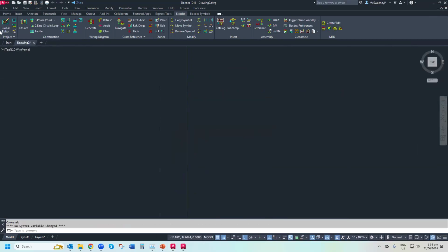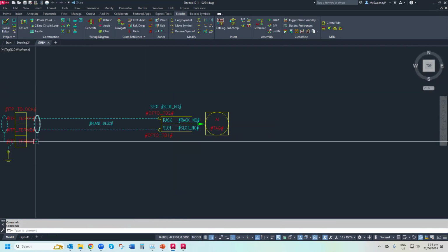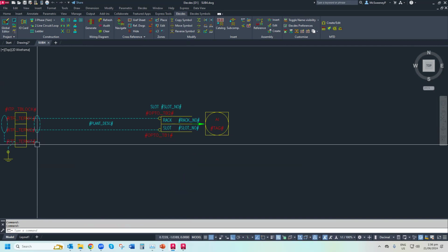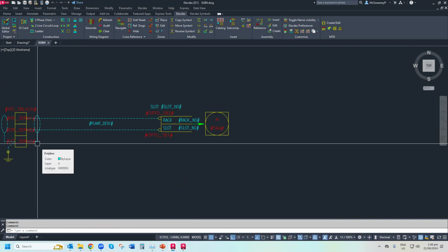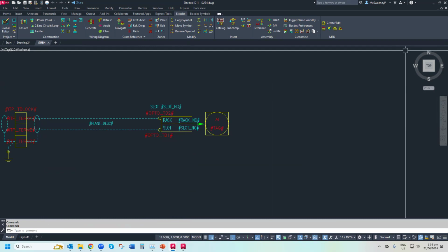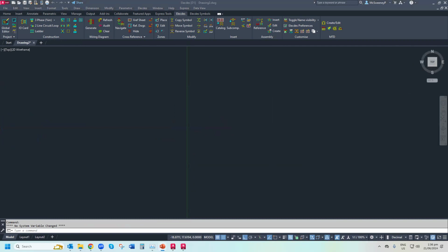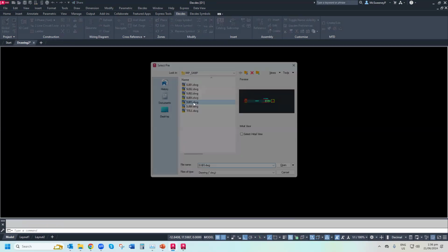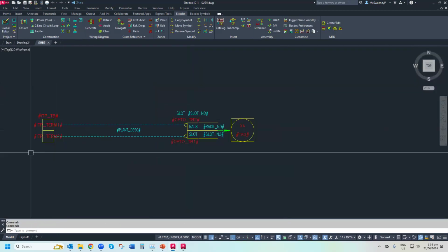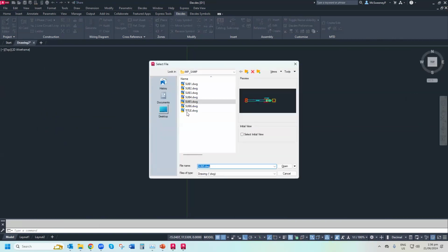And then the next one, we've got a junction box, and there's another point of difference. We might call it, well, we do call it a screen. You call it a shield in America. I've got rack number, slot number for a PLC in there as well. And then if I have a look at the other one, okay, there's one without a screen or a shield. So there are some sub-assemblies. I've got all these, just a couple more to show people.